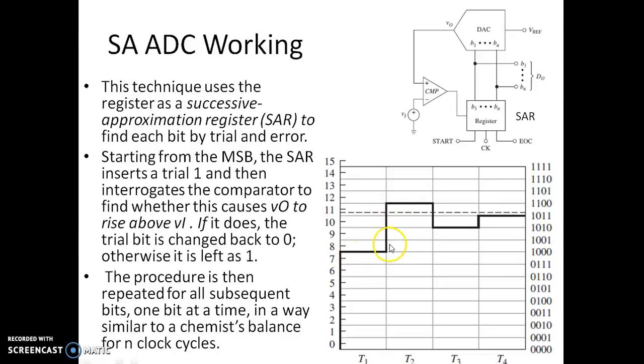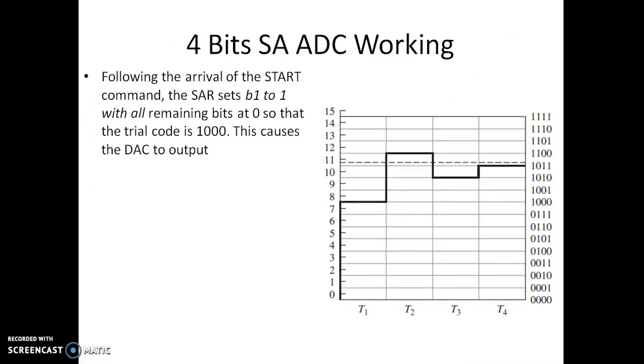Now 1 and all of the bits are 0. Here first two bits are made 1 1 and all of the other bits are 0. Now you can see, since two MSBs are made 1 1, it has gone above the previous value. In such case it will come down. Once it comes down, it makes the third bit 1. So likewise it keeps continuing. This will continue for the last bit. You can see this is how it happens.